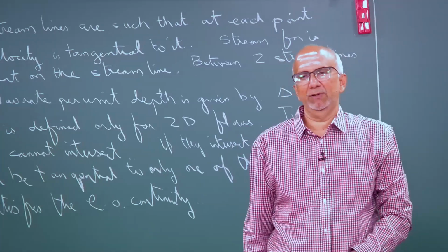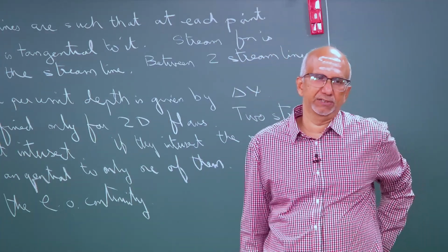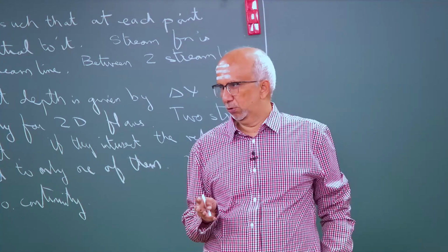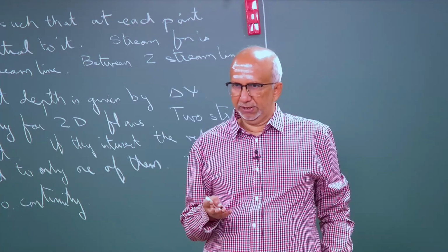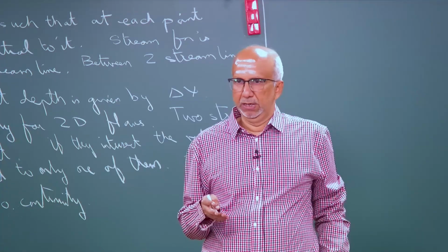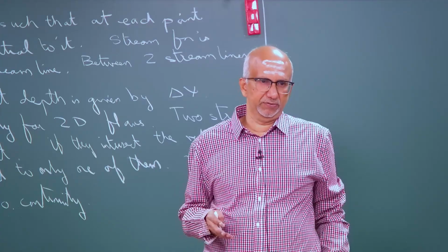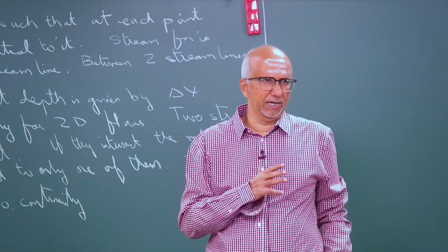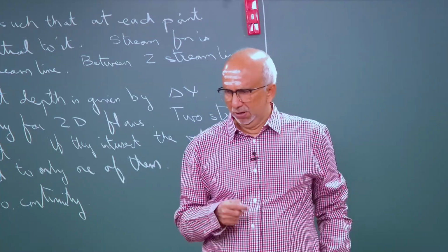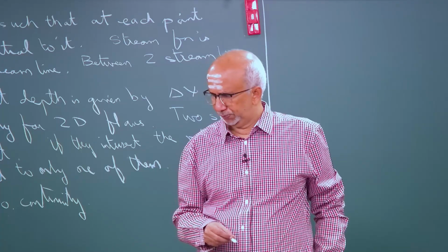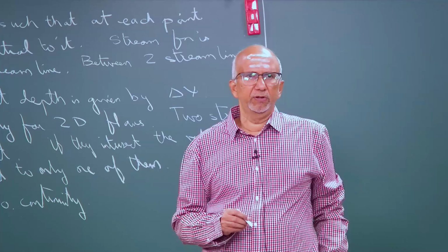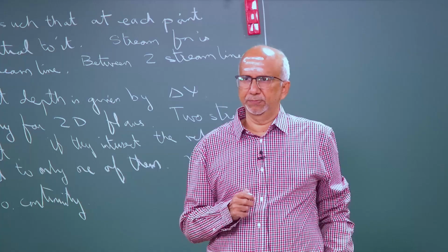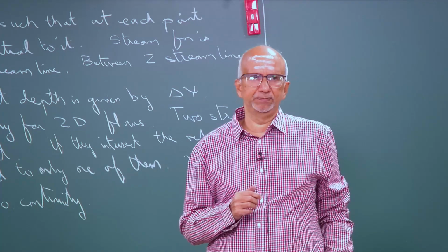So, I have illustrated this in Cartesian coordinates. You can do the same thing in cylindrical coordinates. All these properties have to hold, okay. In cylindrical coordinates, the way you define the stream function should be such that the equation of continuity is satisfied. Same thing for spherical coordinates, okay. 2D flows, everything is just going to translate once you understand the physical concept. Only the math, some derivative may be coming in, okay. So, now we want to see how we can actually solve problems in 2D flows, find the velocity field.